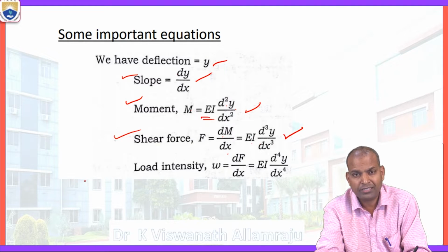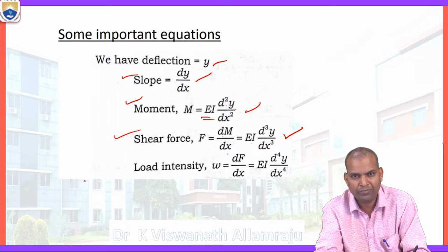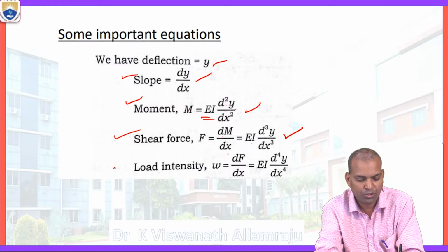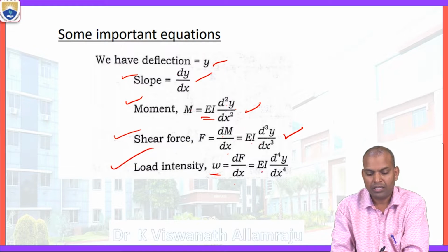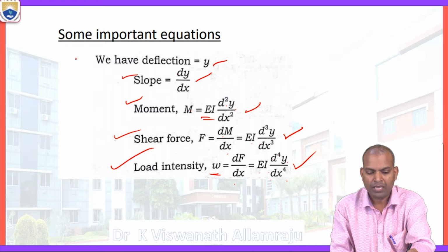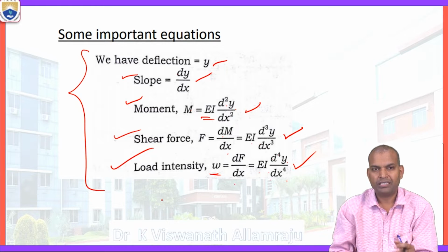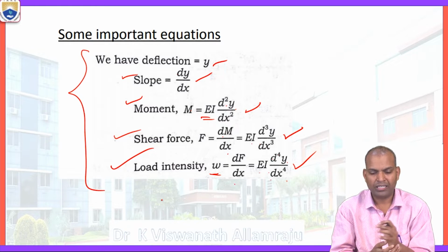Again, differentiate the shear force, dF by dx, which gives the intensity of the loading, that is the load intensity, w equal to dF by dx, which equals EI times d power 4 y by dx power 4. So these all have certain important interlinking relations.